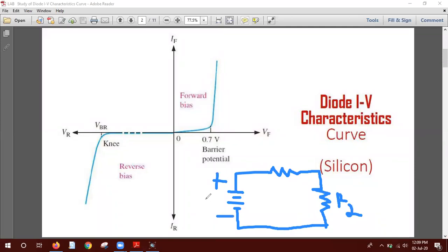So you can connect the voltmeter in parallel. Yes, my student, excellent, in parallel. So we have to connect the voltmeter, the positive terminal here, the negative terminal here. Suppose this is the voltmeter, it should be in parallel connection. Why? Because we all know that in parallel, the two branch voltage is the same. Is it clear?